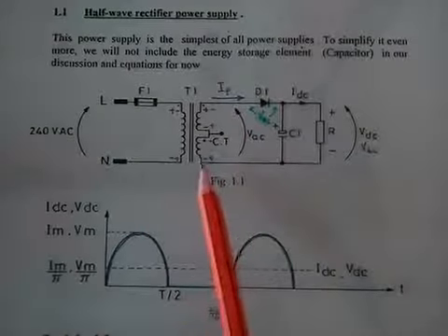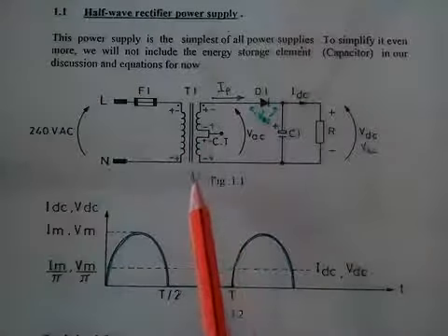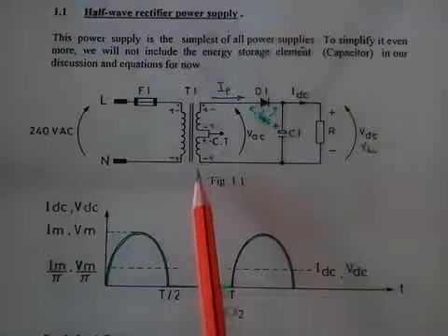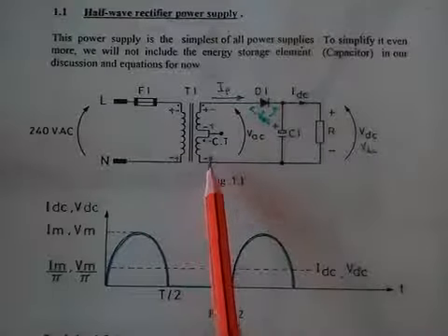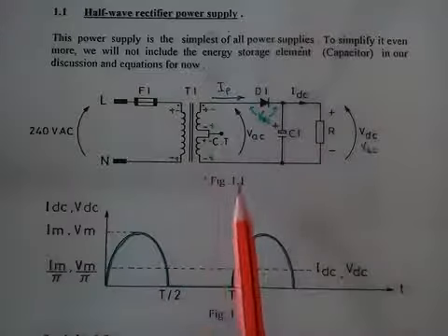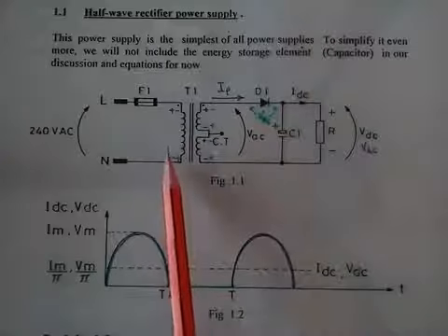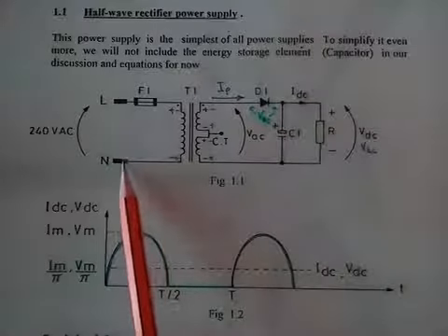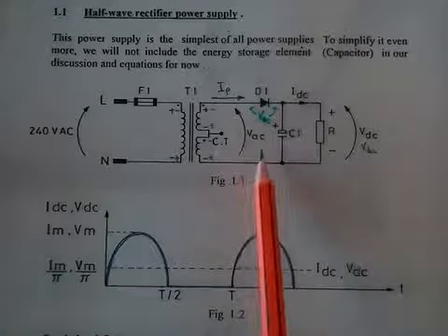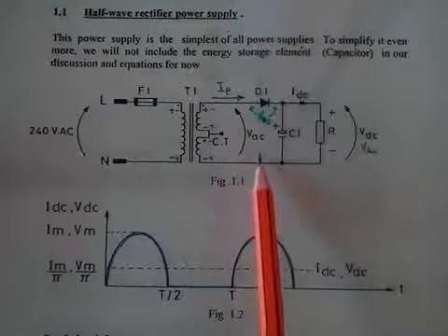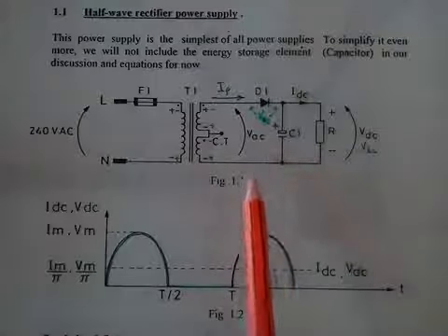You have to note that in all transformers, this is an isolated transformer, the secondary is magnetically coupled to the primary. Therefore, even though this side is referenced to the neutral, and neutral somehow is referenced also to the earth, this side will be floating. So you can practically reference it to anywhere you want in the system.